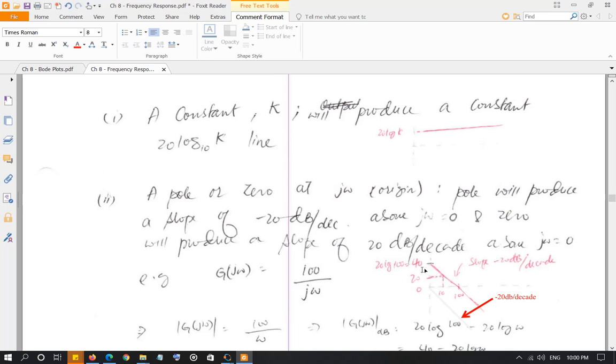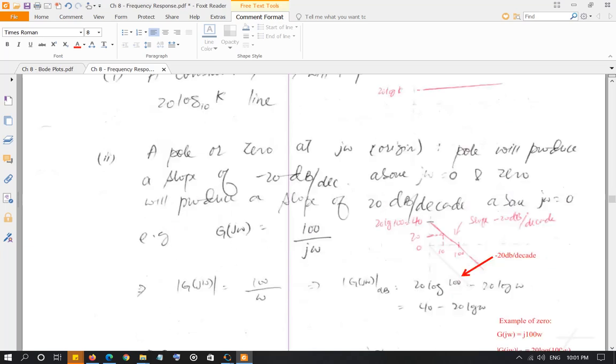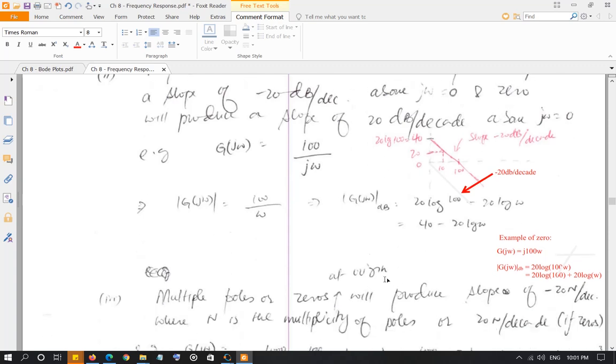the third project from this, where you have to draw the Bode plot, but that project is easy. You don't have to break it down into individual factors. All you have to do is, you have the G(j omega), just take the magnitude of that, multiply that by 20 log, and then plot that versus omega. That's all you have to do versus the semi-log scale, right? So I'm going to discuss the project as well, but the project is very straightforward. So if you have any question, then again we'll discuss that, but this is basically what chapter number 8 is.